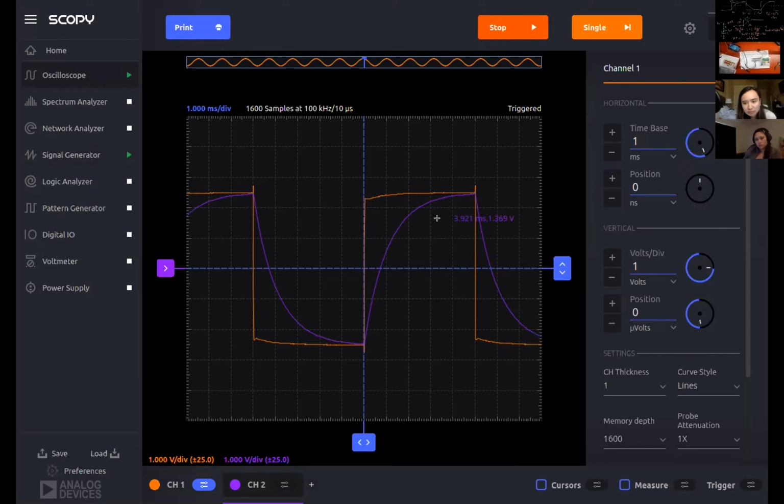Now what you see coming out in orange isn't the world's nicest square wave. And actually the reason why that is because when it first switches, a huge amount of current has to flow to get this capacitor to charge. So it's not really able to maintain this 5 volts super, or I guess 2.5 volts. It's 5 volts peak to peak. It's not able to maintain this super well in the beginning. So it takes a little bit of time to level out. But you can see the pattern here. So it's going to asymptote up, asymptote down, asymptote up, asymptote down.